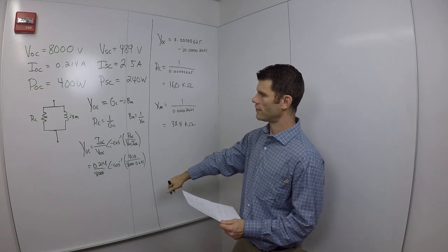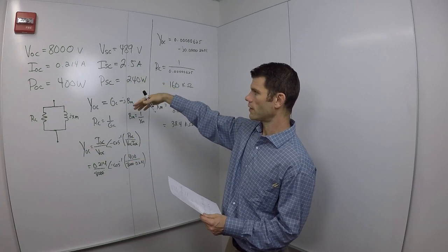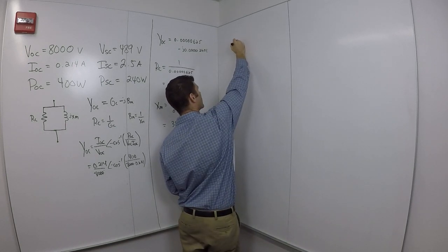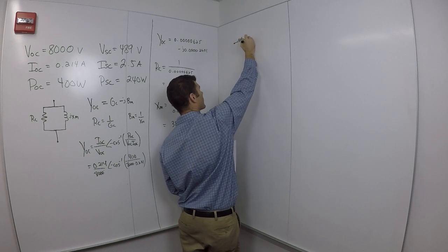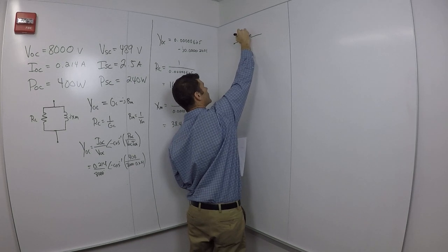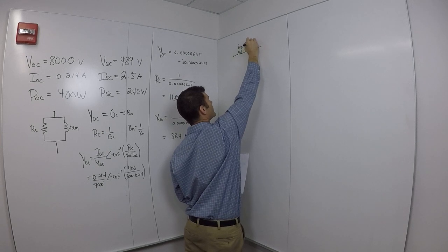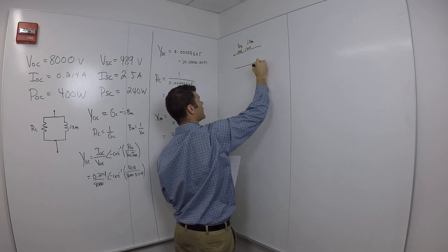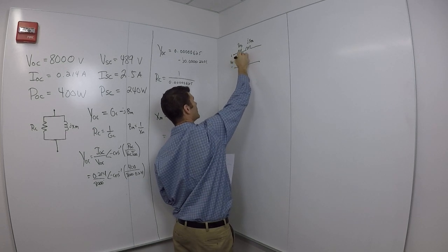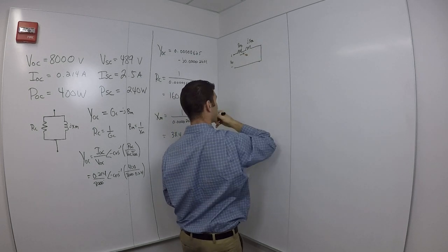Alright, so that takes care of the excitation branch. Now we use the short circuit data in a similar way to find the rest of the circuit. So remember, we couldn't find the primary and secondary components, but what we can find is a combined value. What is the primary plus the secondary referred to the primary side? We can find this because we know the voltage applied right here is VSC. The current flowing through here is ISC, because this is short circuited here.